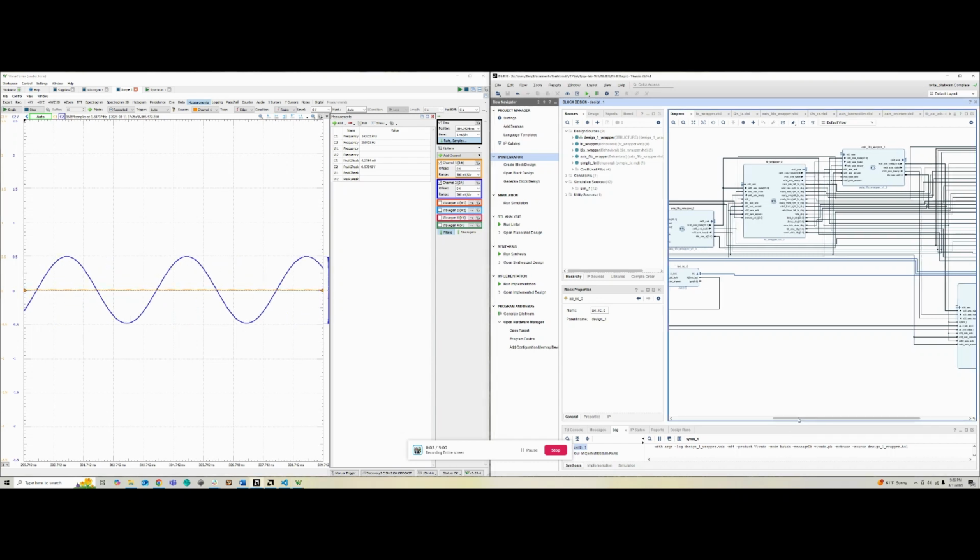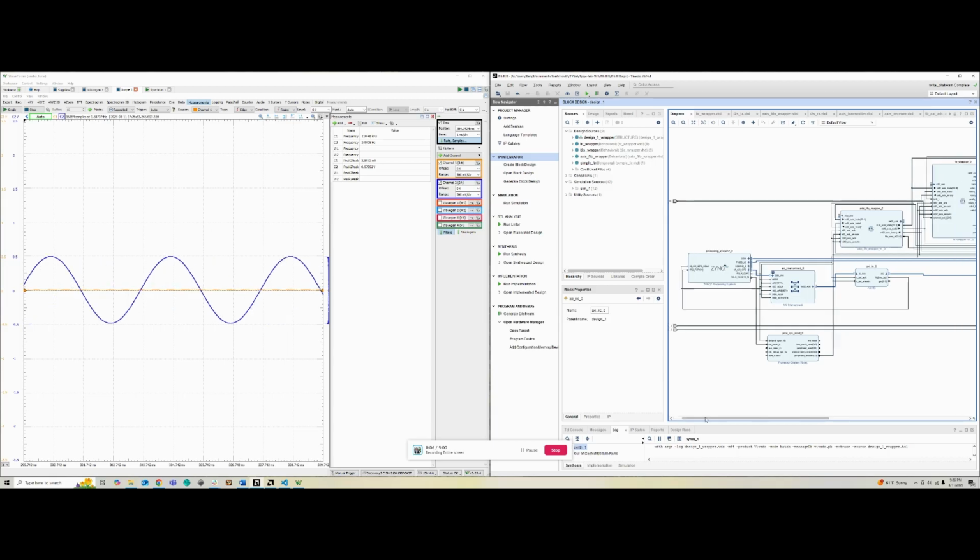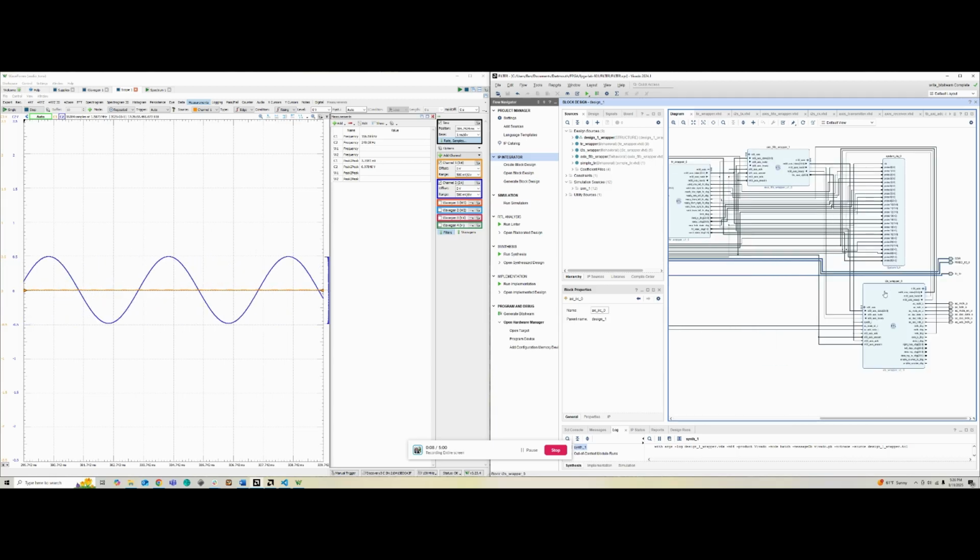So this is going to be design description and hardware validation of my FPGA design panel project. We can start first here briefly with my block design, where I have an I2S wrapper with some external signals communicating with the audio codec on the SoC.